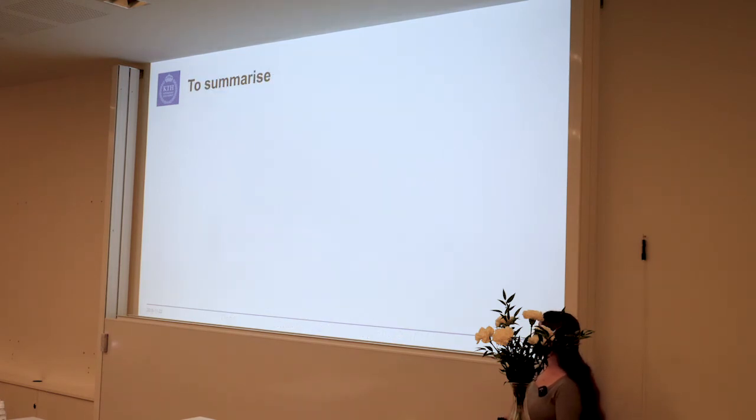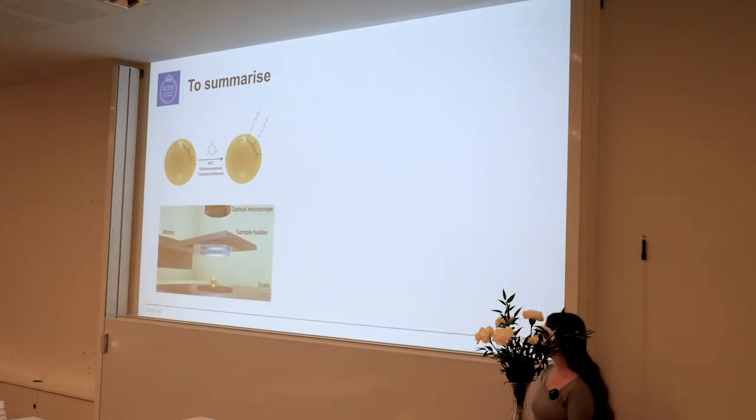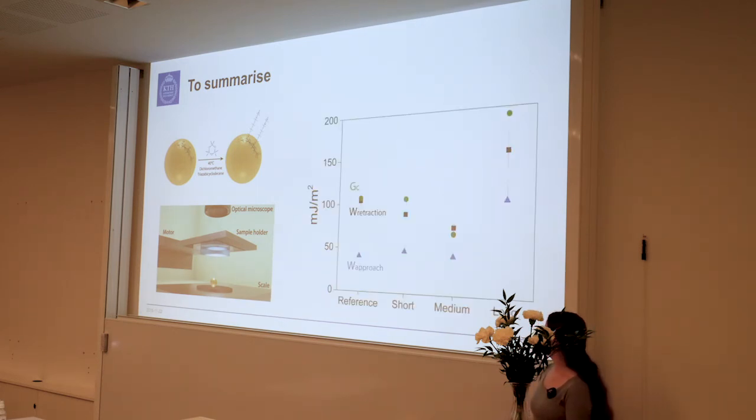So, a short recap of this part, or this track, before moving on to the third one. We used those nanometer smooth cellulose spheres and chemically modified them by grafting PDMS from the surface using ring opening polymerization. We then used those spheres for adhesion measurements in the contact adhesion testing setup, and found that when we were above the critical entanglement length of the polymer for the grafts, we had a substantial increase in adhesion.